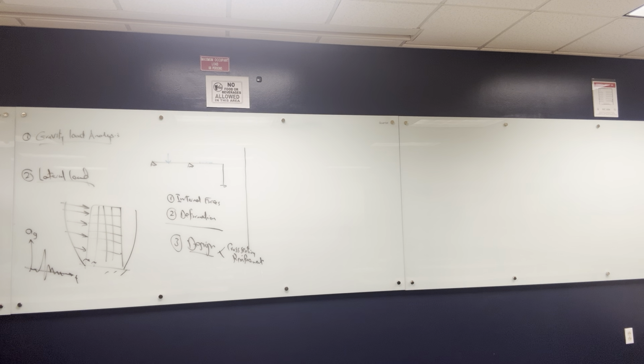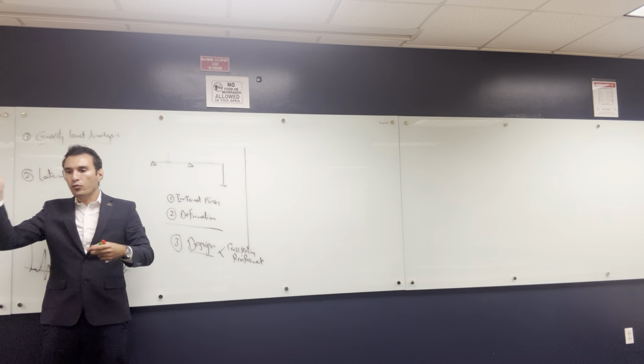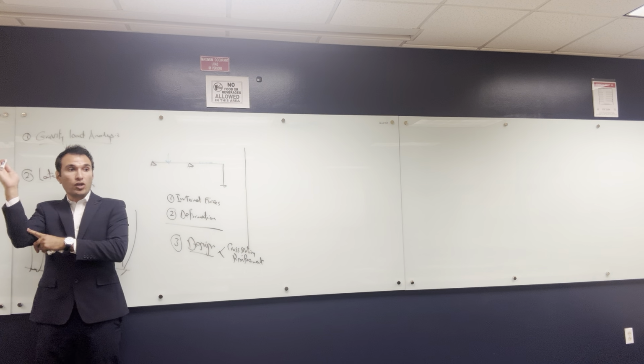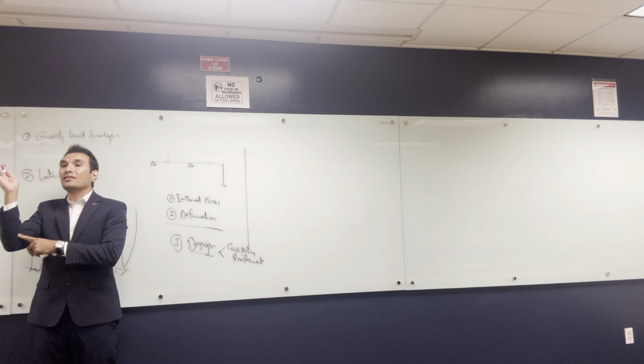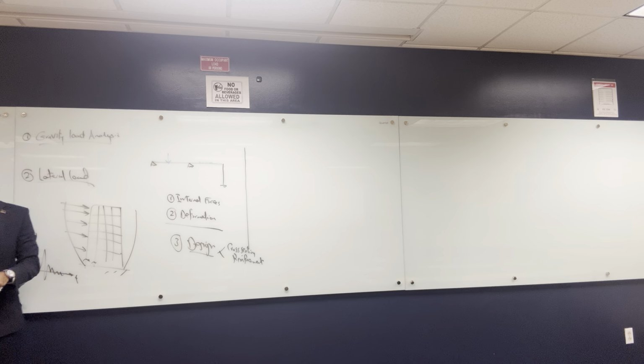Maybe you designed this building to resist the earthquake, but if I live in a 60-story tall building and the building is moving and makes a 1 meter displacement at the top, coming back and forth, the building is not falling, but I'm on the 60th story and the water in my cup keeps moving that way. It's not comfortable at all to live in this building, okay? That's what we call serviceability.